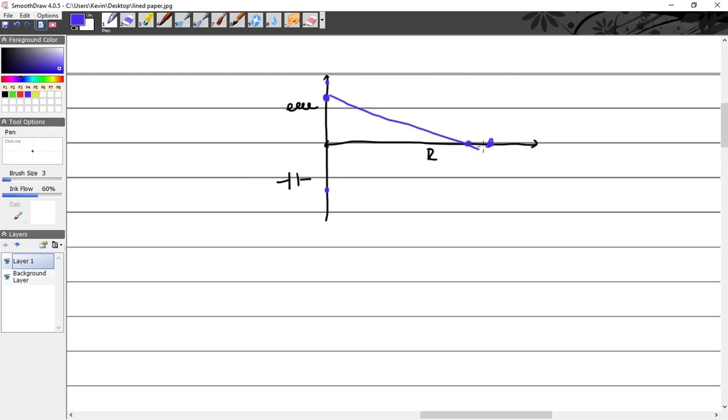I missed the line there because it's harder to do than you think. Here's my impedance. So what did I end up drawing? A triangle, a right triangle. If I know my resistance is X number of ohms, which is given, and you figure out your inductive reactance over here, which is a known quantity, all you have to do is figure out this right here. To figure that out, I just made a triangle, right? There's a formula. If you know this leg and that leg, then you know how to figure out the, what is this called again? Hypotenuse. Okay, and we'll talk about that.